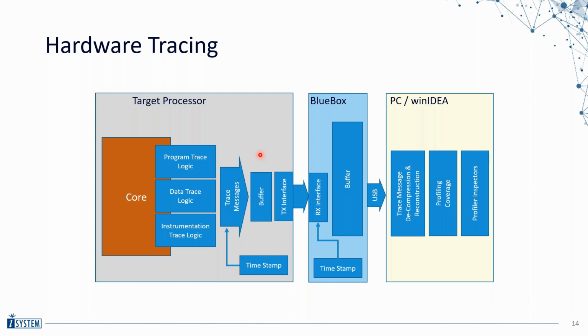But again, it all depends on the microcontroller. If you want to get more specific, it's best to contact us. But those are usually the solutions that are available. If you don't have the trace interface and you don't want to change your PCB, an emulation adapter is usually the recommended solution. On some other architectures, I just want to mention it for completeness' sake.